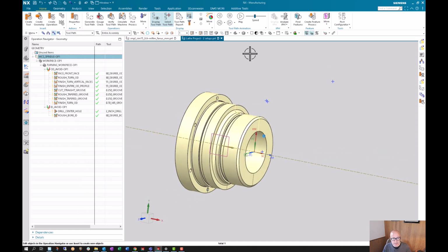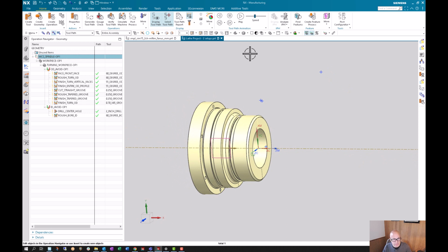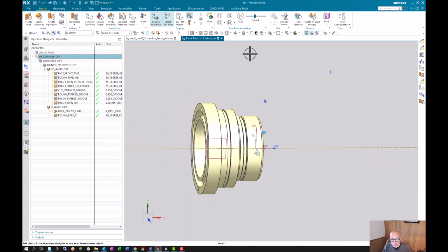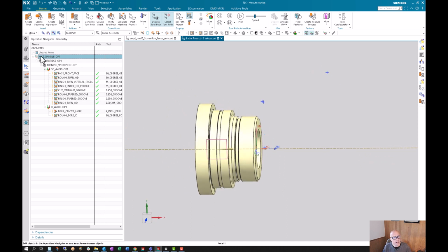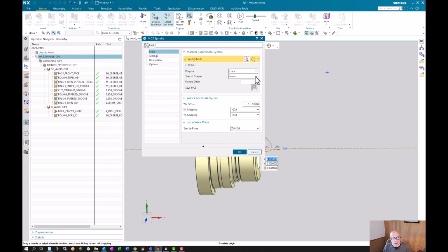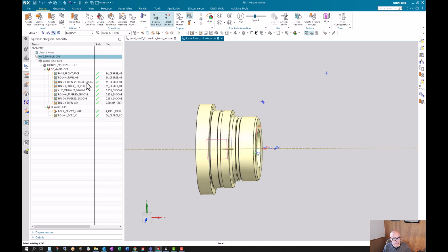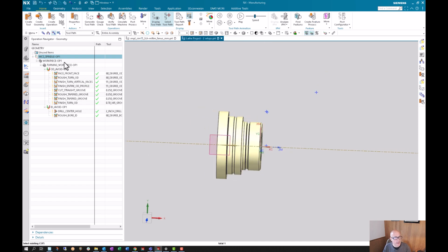It shouldn't make a difference, although also I think if yours is operating from a post, it doesn't need main. So you might be able to drag your spindle out that's local out of the main and just have it by itself. But what I did before copying this is I kind of just did an F2 rename and added op1 to the end of everything.